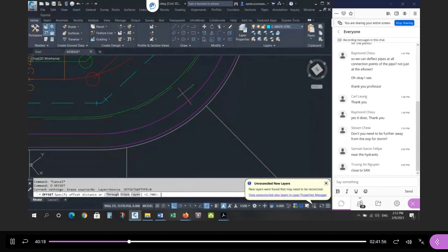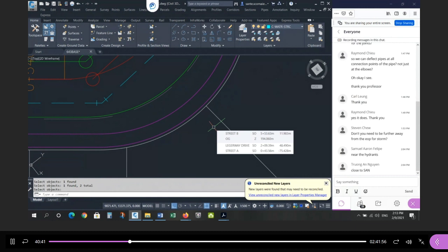Okay, so if you put it in the other position, if you offset 1.7 here and 1.5 to the other side, right? If you did that, right, if you kept a constant boulevard width but made this wider, it's not the preferred solution. Okay? This is really consistent with what the other designer did. It's very subtle, it's hard to see, but these are the details you need to look at to decide how to proceed. Okay? Some of you did it this way, some of you did it the other way. Neither of them is wrong, but this solution is preferred because it was proposed and accepted before.